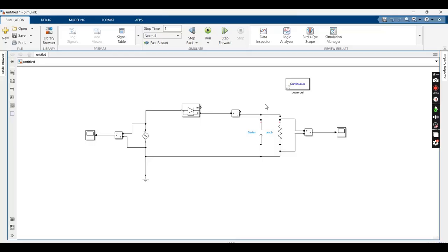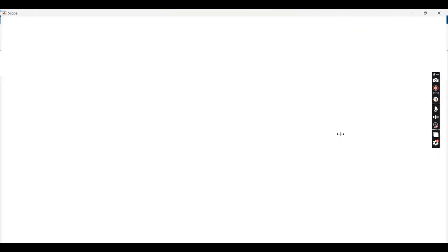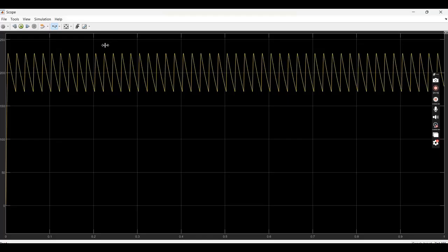Instead of dropping to zero during the negative half cycle, the voltage will decay slowly in a diagonal line. So we can clearly observe the gap is filled and the waveform looks like a jagged sawtooth line near the top of the peak. This is known as the ripple voltage.